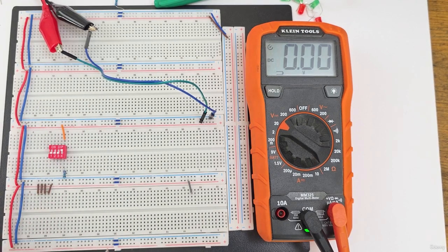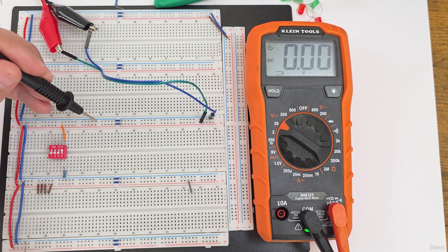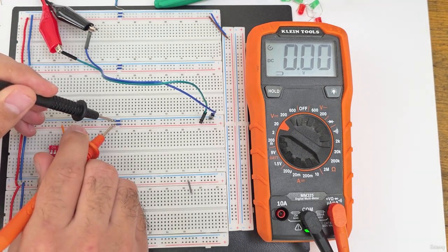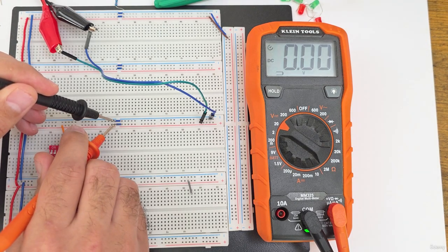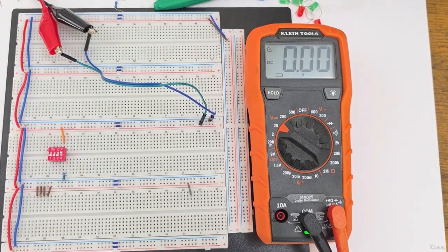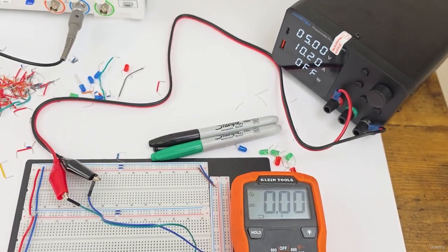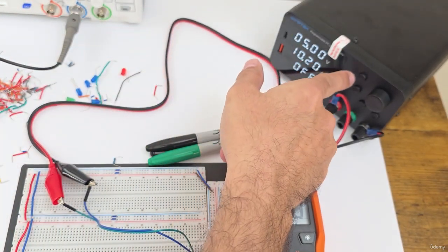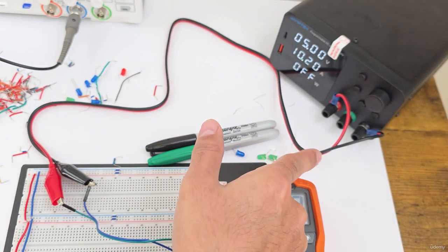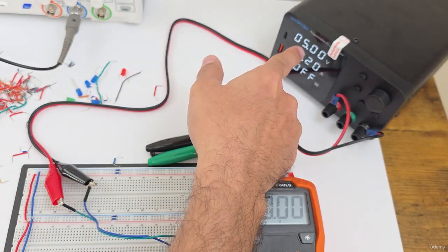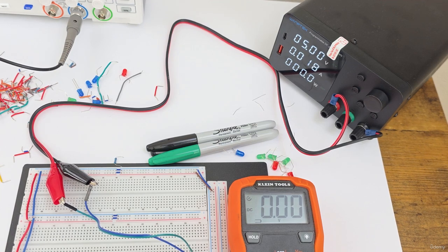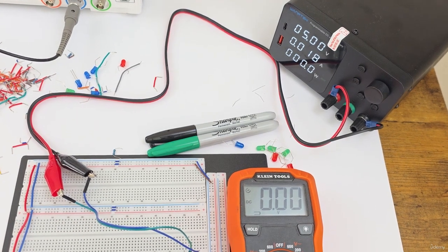The first step to diagnose your circuit is to measure the power supply output. So we need to come here, and here you can see that we have 0 volt. So the power supply is not working, although you can see that the power supply has an output 5. The reason for that is this power supply has a pin to turn the output on or off. Although you can see the 5 volts here, it is not gonna work unless you click this output pin. So now we are ready to work.